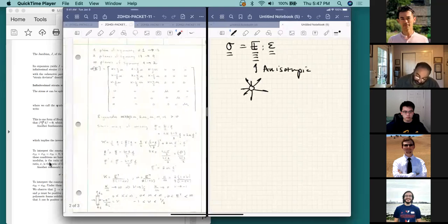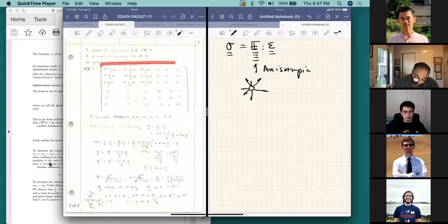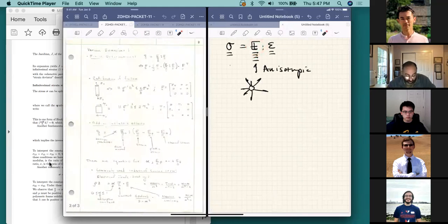We're left with a constitutive law where the elasticity tensor has only 2 parameters, kappa and mu, and combinations of those construct every one of the parameters in the elasticity tensor. We've just gone through all of that, so there's no reason to rehash it. But I think packet number 11 gives you all of the key components of what is important for the last 5 weeks.